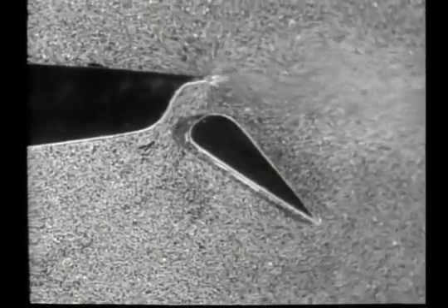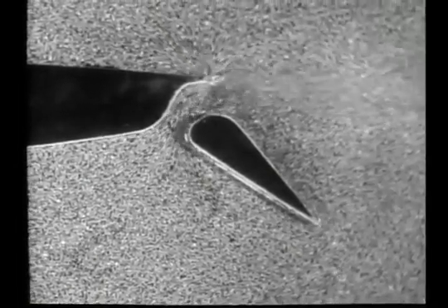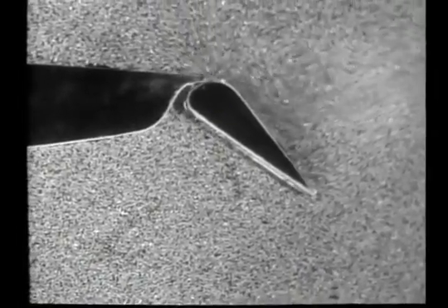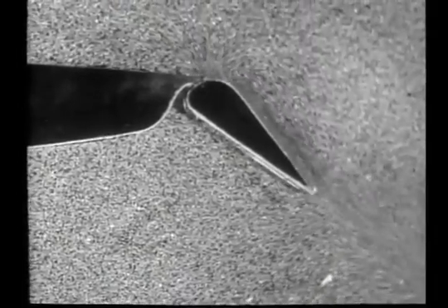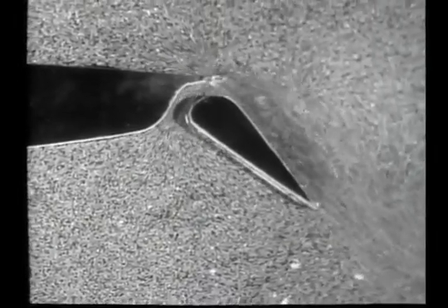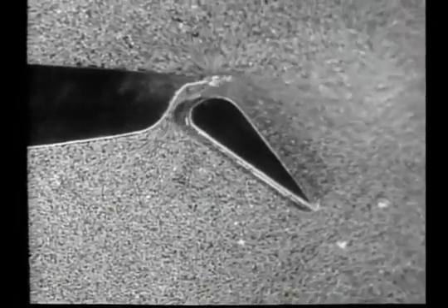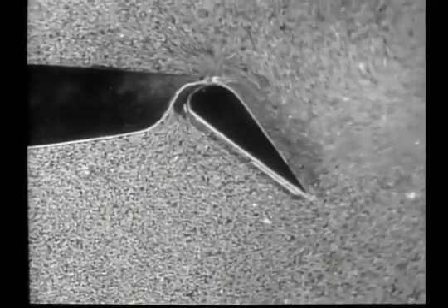When such a high-speed jet is near a curved surface, the interaction of the boundary layer with the jet causes it to bend and to adhere to the surface. This is called the Coanda effect. Here it is used to conduct the jet momentum to a region where separation is most likely to occur. Air can be blown from the fixed portion of a profile to increase lift by preventing flap separation.